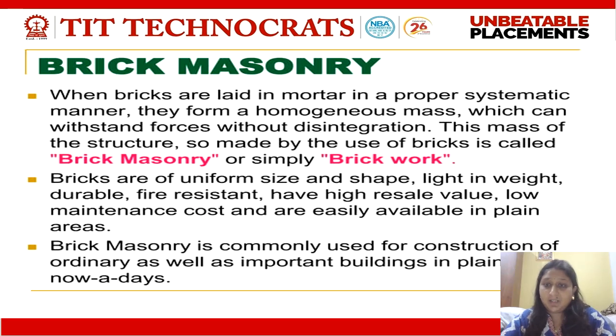Now, depending upon the type of building block used, broadly there are two types of masonry work. The first one is brick masonry. When bricks are laid in mortar in a proper systematic manner, they form a homogeneous mass which can withstand forces against disintegration and sudden impact. This mass of structure made by using bricks as building blocks is called brick masonry or brickwork. Bricks of uniform size, light in weight, with proper properties, good strength, and hard enough are used to create a strong element of a building.